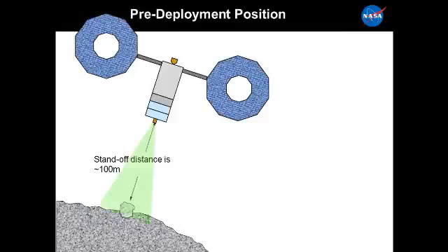So you would fly to a state where you're basically stood off at a certain distance. The sensors we're talking about using here are basically the same sensors we would propose using on the reference mission. Cameras, but primarily closing the loop around a 3D LiDAR. So at that point, you basically have established the spacecraft attitude, you know what the target is, you've done whatever evaluation of the target beforehand, and say, this is the one we're going to go after. Next chart.